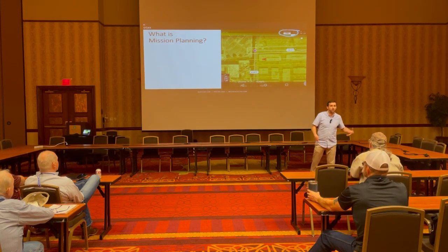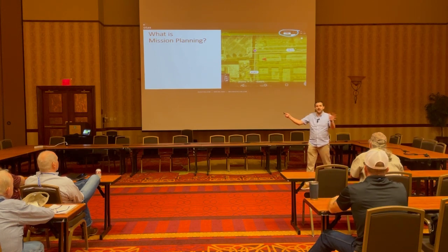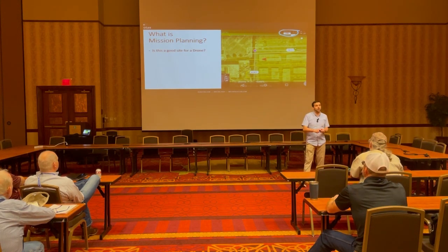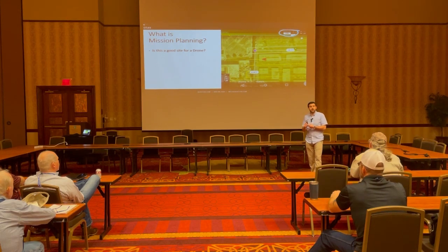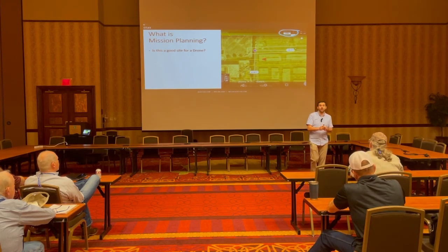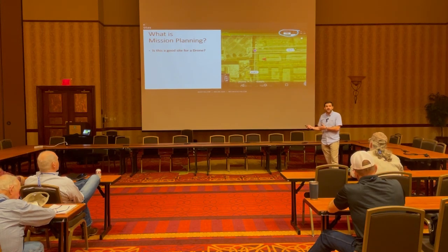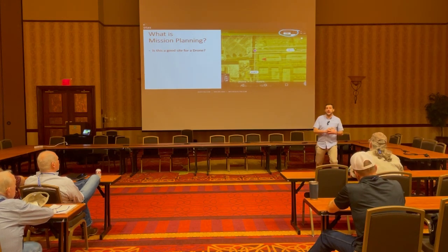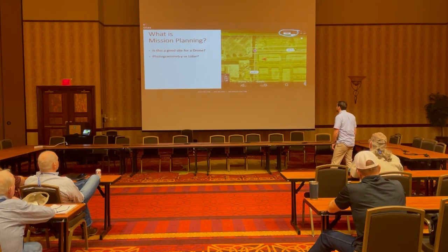So what is mission planning? Why am I talking about it? Why is it not just fly the drone and then magic, magic, magic data? Well, mission planning is first asking, is this a good site for a drone? That's your quickest way to save money on a drone, is not use it when you're not actually going to use it. If you're doing a half-acre site, then it probably doesn't make sense to fly the drone and process the data and run through photogrammetry and accuracy checks and then extract data and then combine it. Too many steps, too much workflow for a very small site, typically.